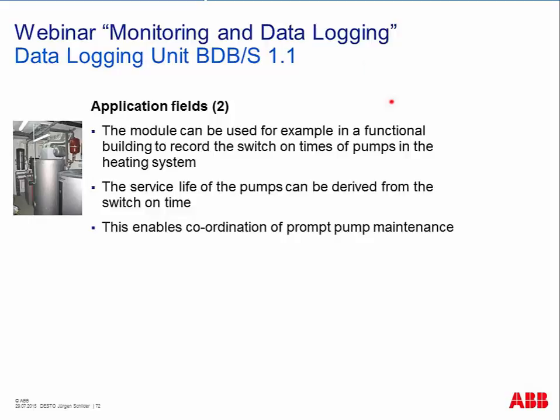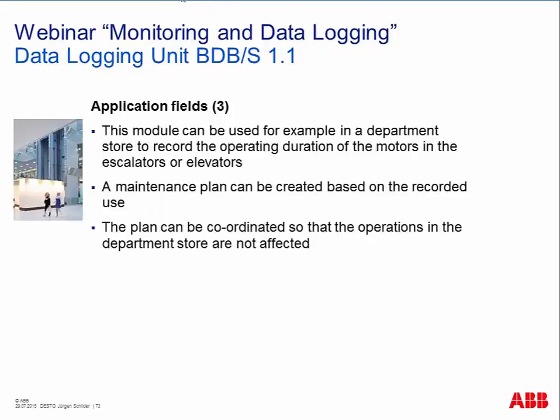Another application field is, for example, to record the switch-on times of pumps or motors, for example, in heating or cooling systems. So every time the motor switches on, we count the switch cycles, and then after maybe so many thousands of switch cycles, we get the information that we have to do the maintenance.